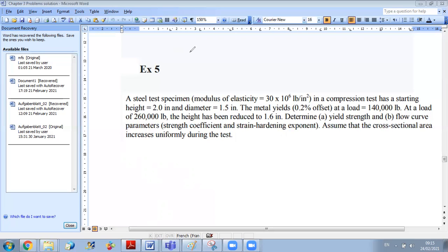So I have first the sigma axis and the epsilon axis. This is on the engineering curve, and I have the variation of sigma with epsilon. First I have a nearly linear profile, and after this I have a transition. After that I have the strain hardening zone, and after that I have rupture. Okay, this is the profile of my graph.